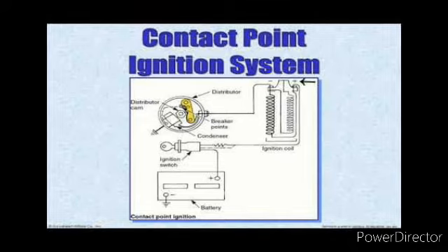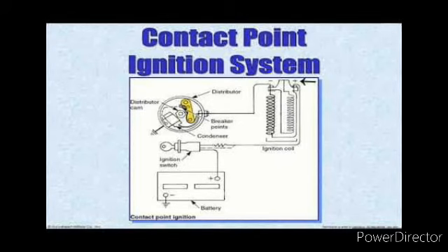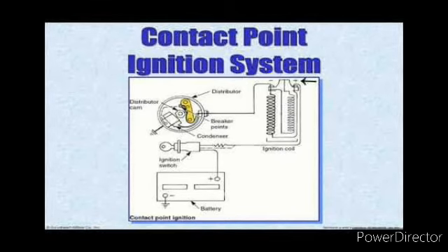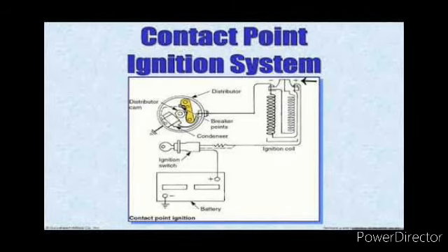The current running through the winding in the ignition coil builds up a powerful electrical field that is unleashed when the points separate. No longer able to go to ground through the points, the electricity, which is seeking the easiest spot to ground, rushes through the secondary circuit to the coil wire to the top of the distributor cap, where it is transmitted to the distributor rotor.